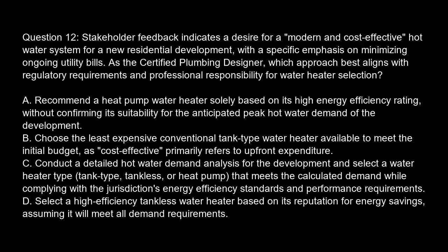Option C. Conduct a detailed hot water demand analysis for the development and select a water heater type, tank-type, tankless, or heat pump, that meets the calculated demand while complying with the jurisdiction's energy efficiency standards and performance requirements. Option D. Select a high-efficiency tankless water heater based on its reputation for energy savings, assuming it will meet all demand requirements.